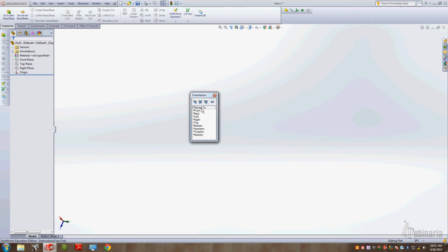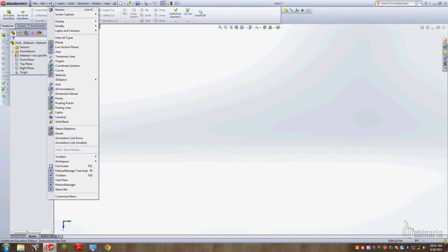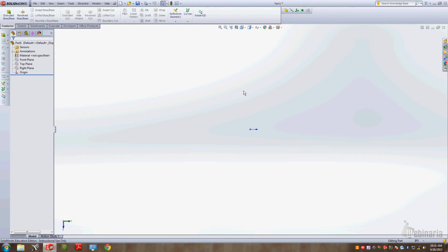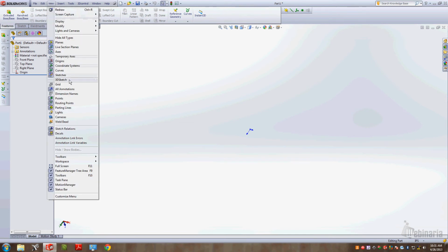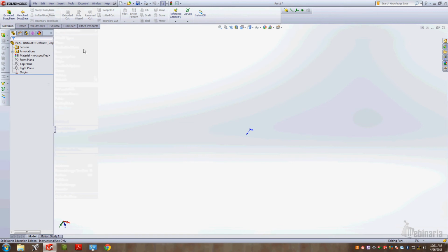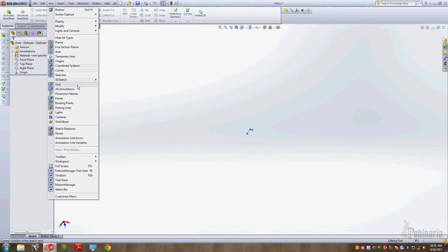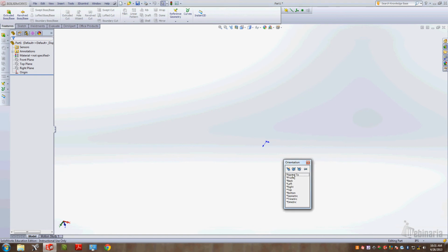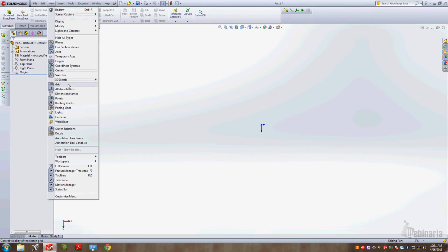Another tool that you'll find to be extremely useful for what you're going to be working on today is if we go up to our View option and we go down to Origins. So I'm going to hit View, Origins. That's going to give me my exact origin that I can draw about. Now to take that one step further, if I say View, Grid, that will turn on a grid for me, or it should anyway, turn on a grid that we could utilize to see our individual quadrants.